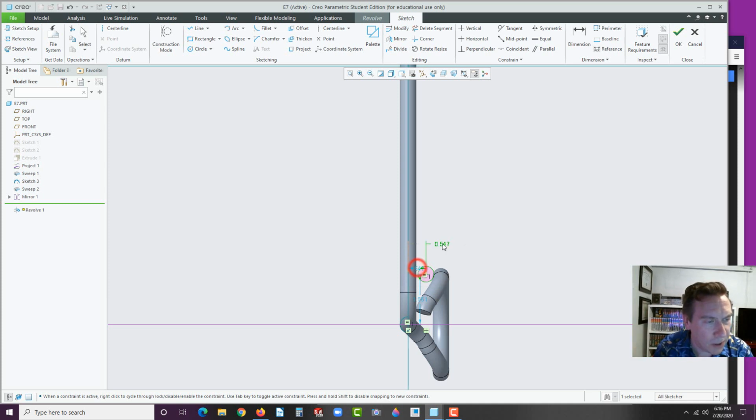Now this dimension should appear right here. Let's make it 0.49. Now I'm having it intersect in about 10,000ths of an inch. The reason for this, if you go tangent to that edge with that circle, Creo sometimes has issues with that. It's a 0 thickness connection point. Now in version 7, they have it where it actually looks at it as though they're multi-bodies, and it should have no problem with it. But this is version 6, so we can't do that yet. So we have to, I would recommend intersecting it, like welding it in a little bit.